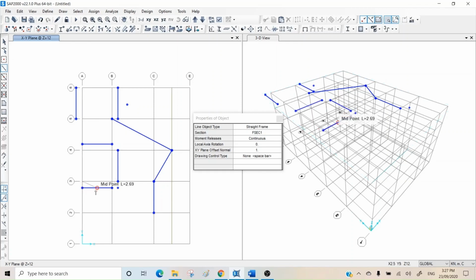The reason is I'll need to talk about local axis, but the local axis is always along number 1, and then axis number 2 is here. So it's taking the positive number 2 as an offset. As I said, I don't want to go through all of them, but there is a logic behind that. I will explain it later when I talk about element local axis, which is in module 2.